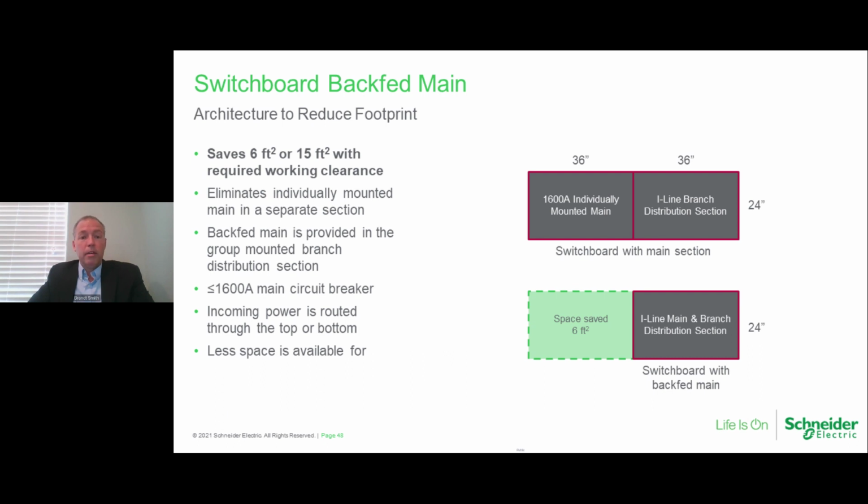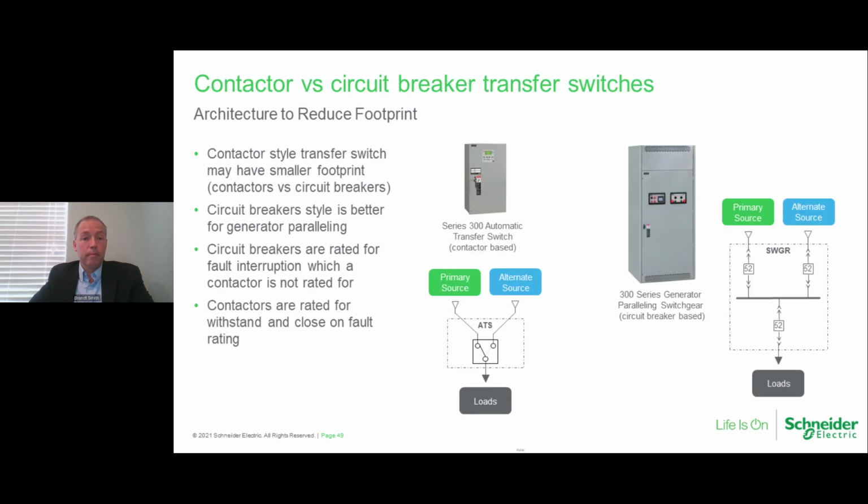Another area to look at: do we really need individually mounted mains? Sometimes you have to do that, but if you can eliminate that and just backfeed a main circuit breaker, you can save an entire section just on the main.